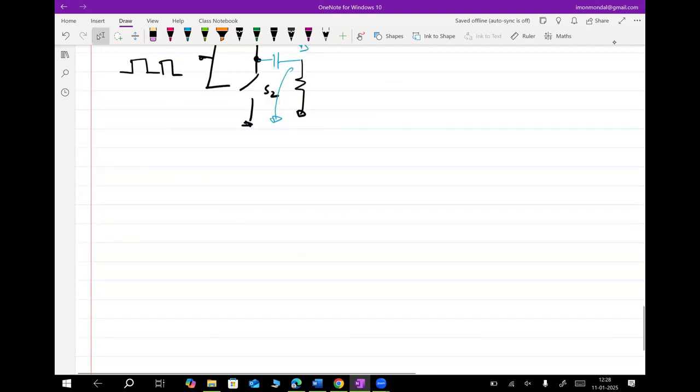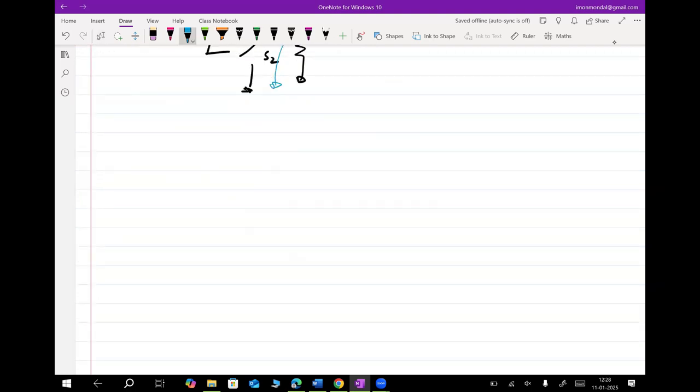We have the transmitter chain, so to say. So we have an input signal, which is VBB, where BB is the baseband signal. Baseband is often referred to in RF lingo as the low frequency input. And when I say FC, C refers to the carrier frequency, because ultimately it is assumed that the high frequency signal is carrying the low frequency signal on its back, right? So ultimately you have to modulate the low frequency signal to a high frequency to ensure it travels through the antenna of a reasonable size.